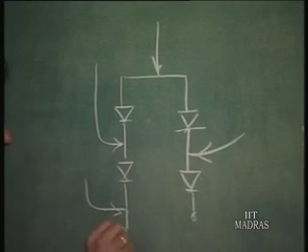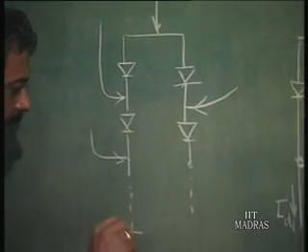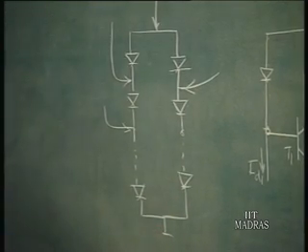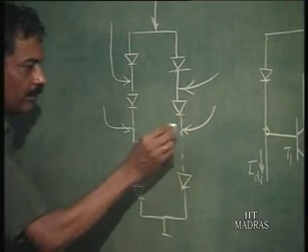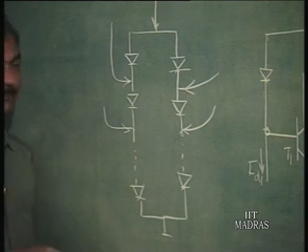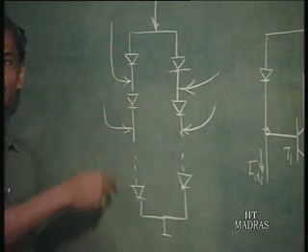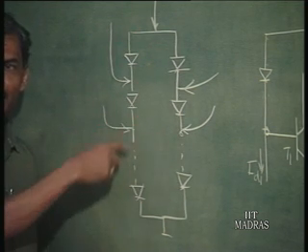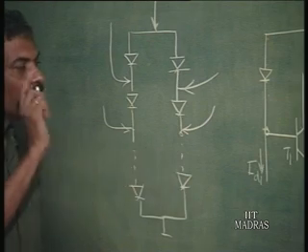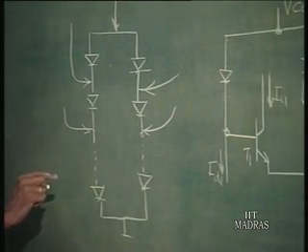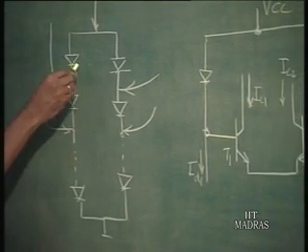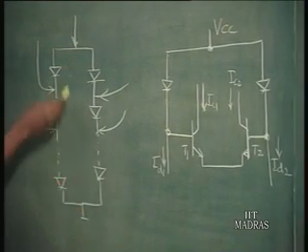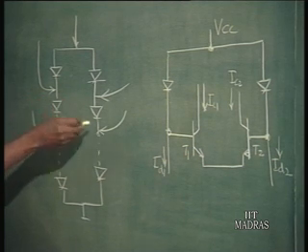So, suppose we have a string of diodes, all of them form a loop, let us say. Then Kirchhoff's voltage law is valid here, that the total voltage in this is 0. Summation of all the voltages in this should be equal to 0. What is required in this translinear principle is that the number of diodes connected in the clockwise manner, let us say these are all clockwise forward biased, these are anti-clockwise forward biased, these numbers should be the same.